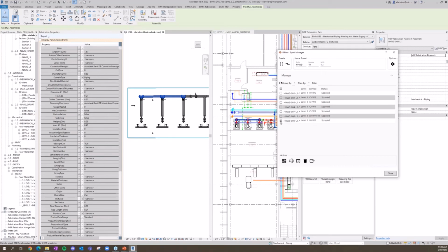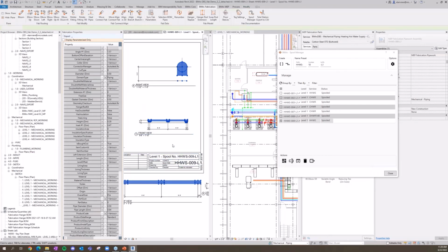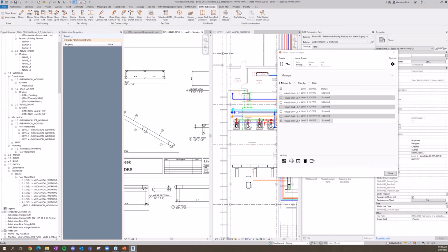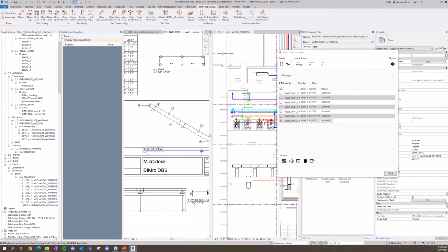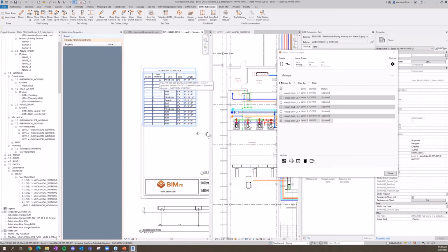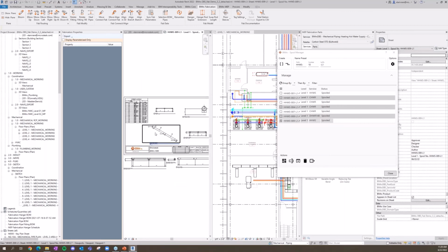And once you've found it and chosen the one you want to work with, we can open those spools up right there with the open spool view, and there we go. There's my auto-generated spool, a couple automatic 2D dimensions, some more 2D dimensions, and I've got item number tags set up to be shown over here, linked up to my item numbers that are showing up over here. How about that? A spool in only a few seconds.